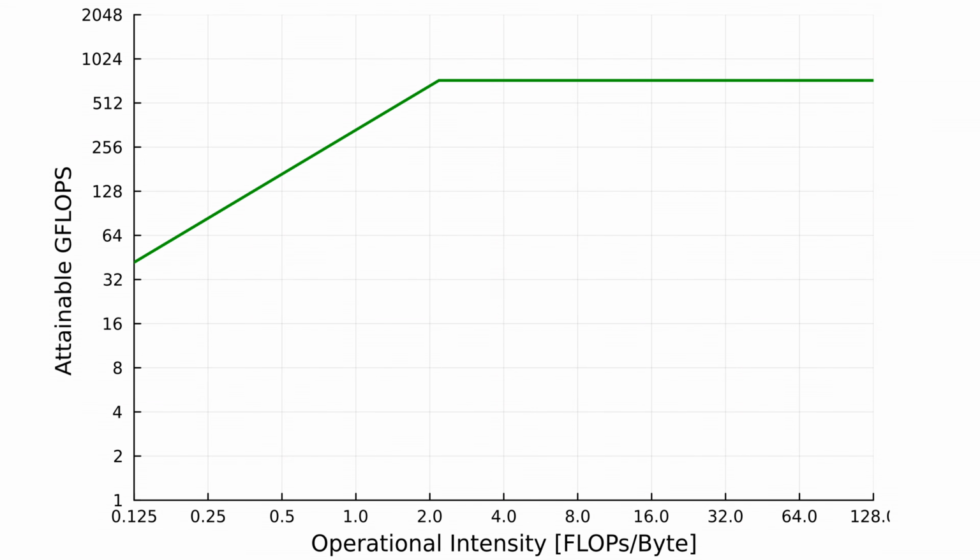There are two dimensions at play. On the y-axis, we have the familiar compute bandwidth in gigaflops, and on the x-axis, we have the so-called operational intensity, which is measured in flops per byte. Operational intensity is the ratio of operations per byte of DRAM traffic, and is a function of a problem's complexity and is not a property inherent to a particular CPU or GPU.